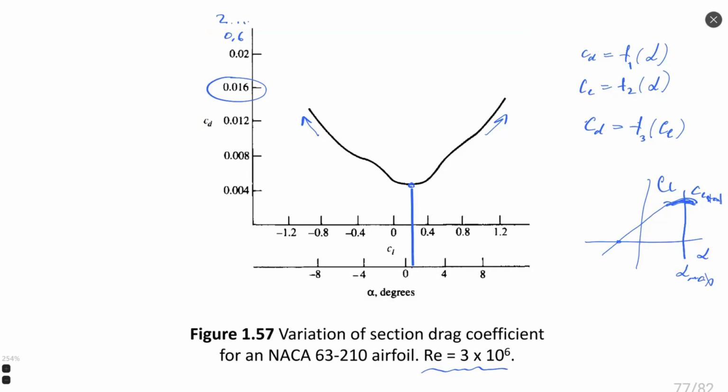Numerical simulation will also give you some estimation of drag coefficient, not very correct in inviscid simulation and much more correct in viscous simulation, because viscous simulation provides shear stress calculation and it's the biggest contribution to drag coefficient. It must always be positive and small for airfoils, and also positive but big for blunt bodies such as a cylinder, sphere, or plates.